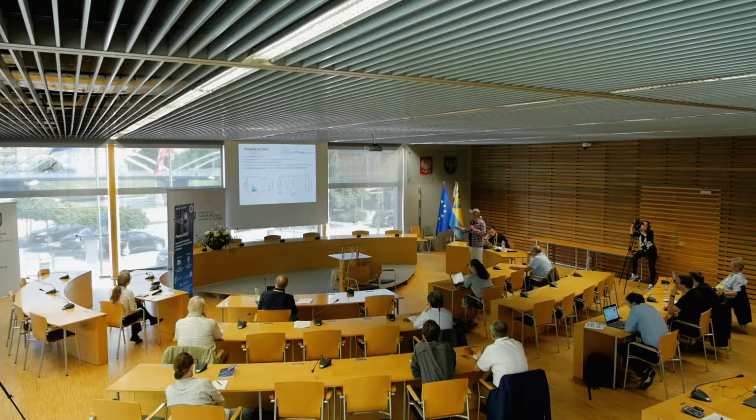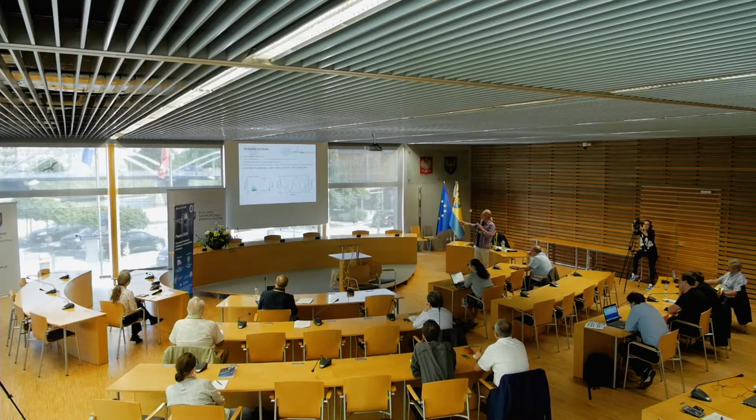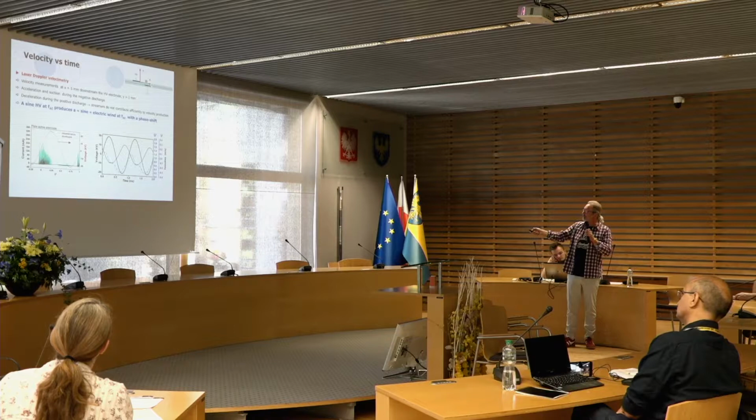And if we measure, for example, the produced velocity with another technique, laser Doppler velocimetry, at a fixed point, we have this sort of curve. Here we have in black the voltage versus time, and in blue the velocity at this point. What can we see?